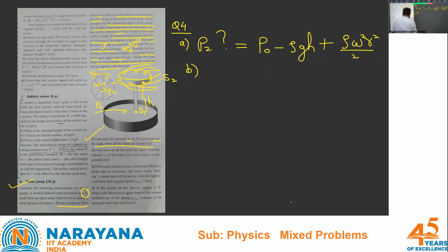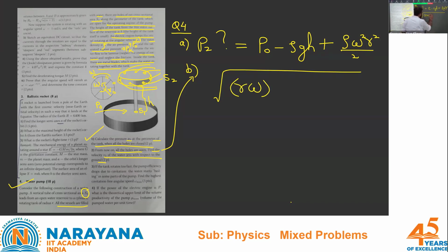B part, he says, from now on, all the holes are open. Find the velocity of the water jets with respect to the ground in the second part. Write carefully, because the pressure that you have got there, and outside pressure is P naught. So that term half rho v square will give you some velocity. The answer to this question should be root of, because they will have two velocities, no? The upper one is rotating with omega, so all the liquid which is coming out will have a tangential velocity, which is r omega. So r omega whole square plus the relative velocity square term.